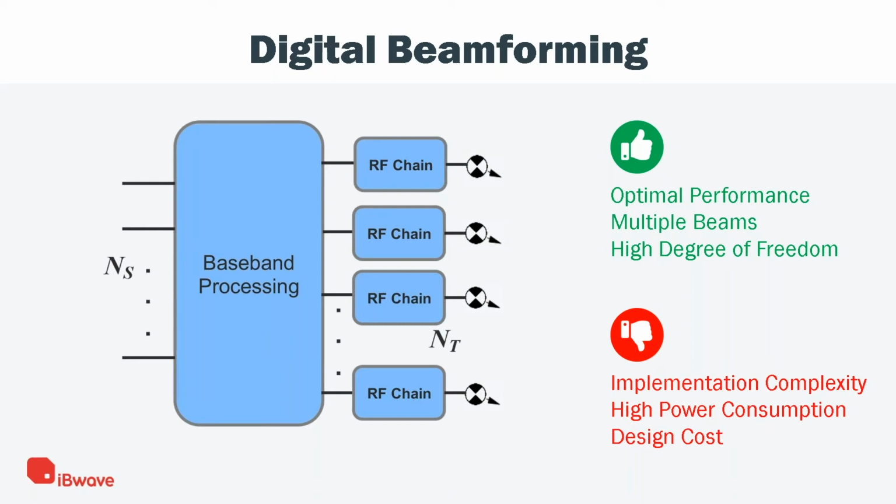Because in baseband we can process different signals, we can have multiple signals, which is the number of streams to be transmitted, and apply this processing to each stream separately. Then the output for each antenna element will be one RF chain, applied to create this beamforming radiation pattern.